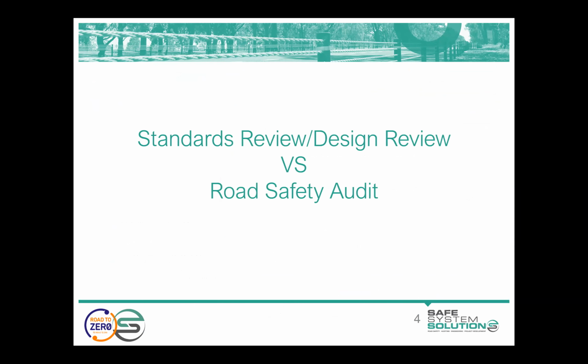So just to start, I'd like to discuss briefly the difference between a standards review or a design review and a road safety audit. There certainly is some overlap between the two processes, and often a client won't be quite sure which of the two they're after. A standards review and a design review is exactly that. It's a check against standards, and there is an inherent level of safety built into standards, but that's not to say that everything built to standard will be safe.